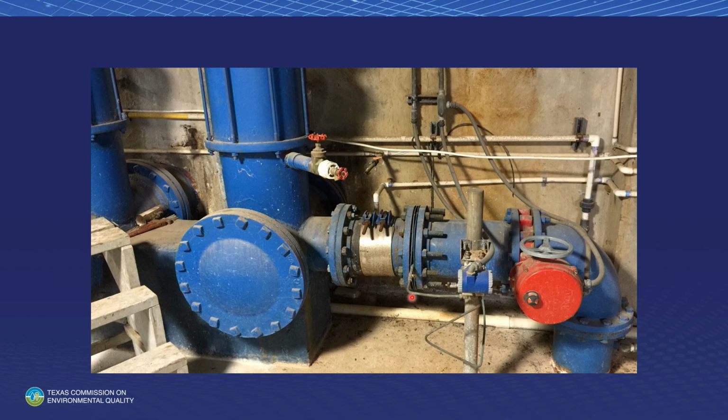There is an orifice plate right here that's used for rate of flow indication. Water comes out. Here's the flow control valve that regulates the flow rate of the water. It goes down into a channel below here that contains the filter effluent from all of the individual filters. That filter channel feeds the clear well, the ground storage tank. Notice that there is one IFE sample line that runs along the back wall, around a pillar, continues on the back wall for several feet, and then they put their turbidimeter in.